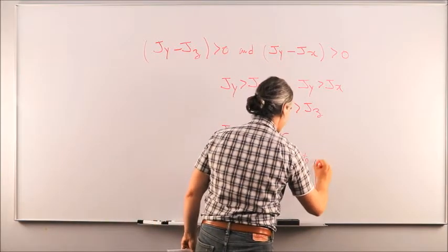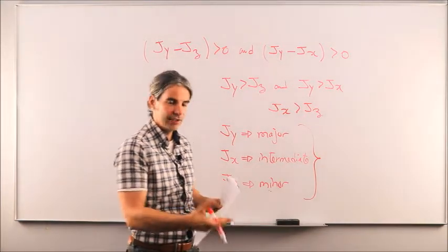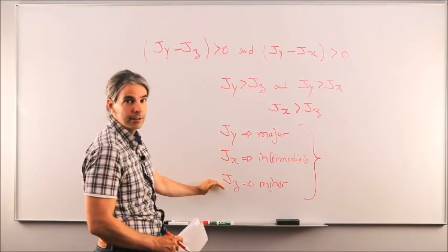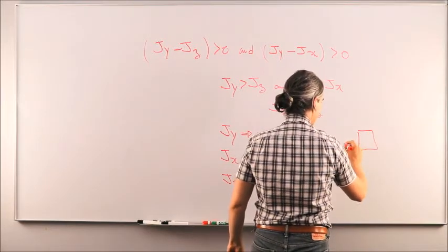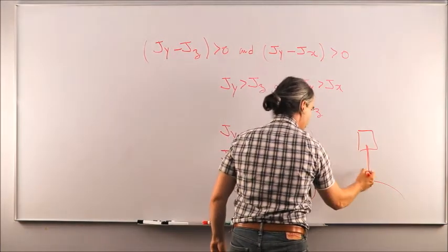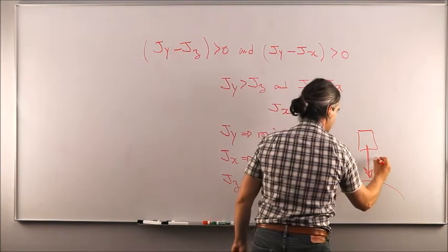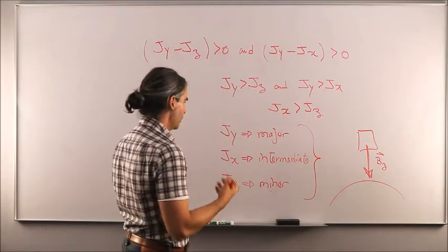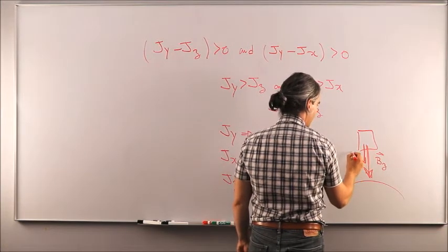If the spacecraft is designed by careful placement of components within the rigid body or mass distribution, to end up with an inertia matrix that satisfies those three things, then naturally the spacecraft will want to align itself with the roll pitch yaw reference frame at all time and maintain the nadir orientation throughout an orbit, okay? But it's BZ unit vector pointing down like that. And the reason why we want BZ specifically pointing down is because QZ is also pointing down.